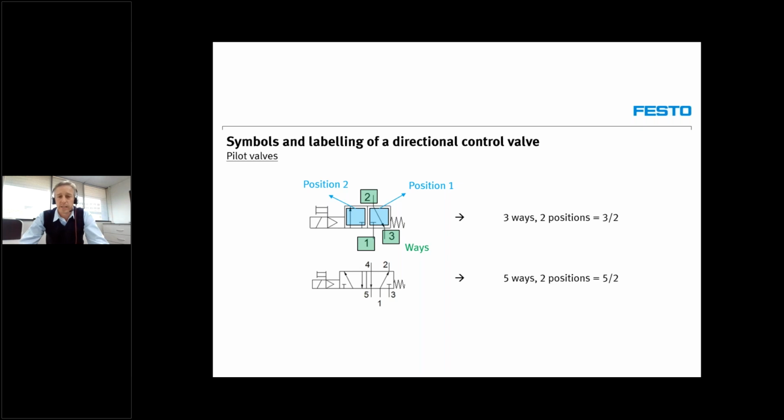That's correct, because the single acting actuator only needs one working port to push the cylinder either forward or backwards, where the spring would do the work of pushing it back to its default position. So that's why we only need one working port for the 3 two-way valve, whereas the 5 two-way valve is used for the double acting actuator, moving the actuator forward as well as backwards by means of air pressure.